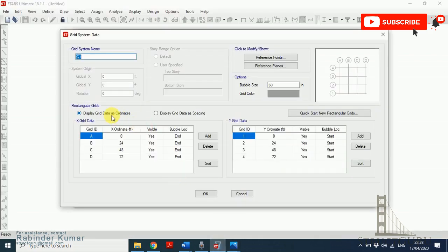In your ETABS model, you can see Display Grid Data as Ordinates or Display Grid Data as Spacing. So what is the difference between them? If you choose the option as ordinates, that means whatever value you enter, you always have to follow from your origin.